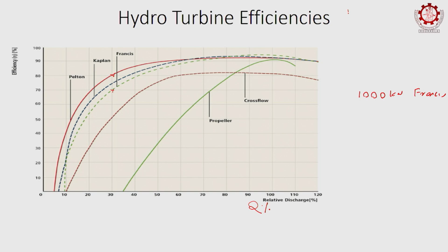Because if you look at your flow duration curve, Q against percentage time of exceedance, it is like this, right. So, a lot of time it will be operating in low flow conditions, your rated flow may be here. There are a lot of time machines are on part loads. Therefore, you are operating at these low efficiency points, which is a disadvantage.